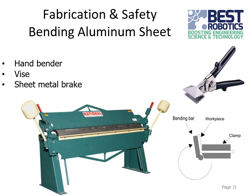If you see that picture down at the bottom right, that gives you an idea of how you want to situate everything. You want flat surfaces on both sides of the bend to help you keep it straight where it's supposed to be straight, and just bend around the part that you want.